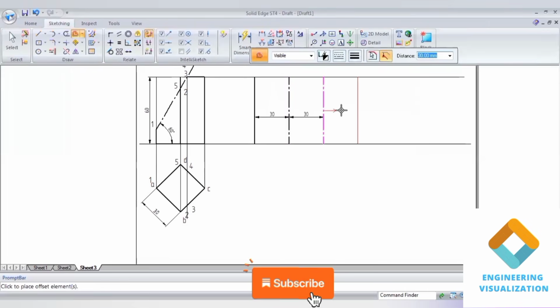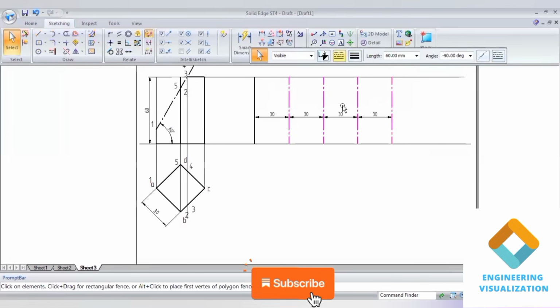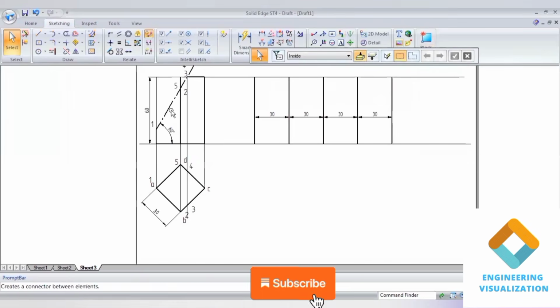Now here you can see the dimension, it is 30. Totally there are 4 faces in the square prism. So using the offset command, I will give the distance of 30, and then click 4 times. I will get the 4 faces here. I will make all these lines continuous.